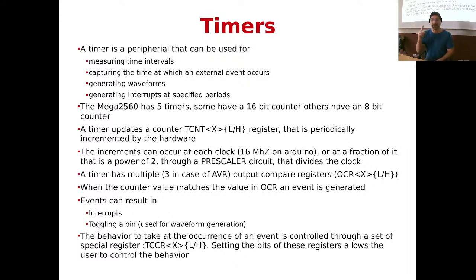Okay? Second way. You can generate waveforms using timers. How? You configure the timer to say, hey, dear timer, start counting forever, and once you reach this value, please toggle this pin. The timer counts on its own. When it reaches the value that you told it to reach, it says, oh, sorry, pin down, and then up again. But this is not done by the CPU. You don't have to write a program that deals with the pin. This is done by the timer itself.